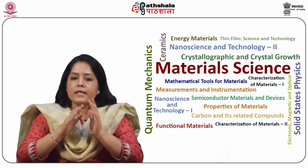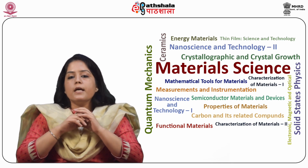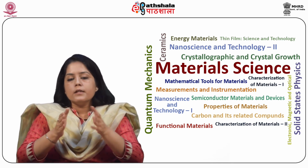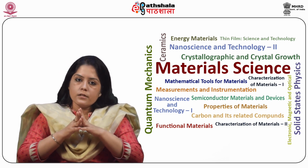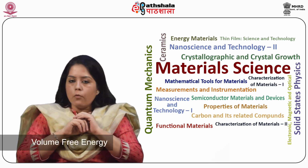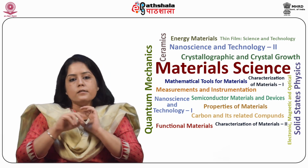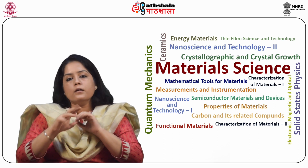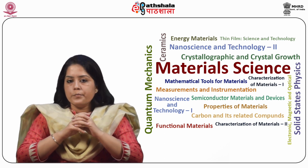Formation of interface leads to an activation energy barrier. So here the energy changes are associated with first the volume free energy, second the surface energy, and third the misfit strain energy.